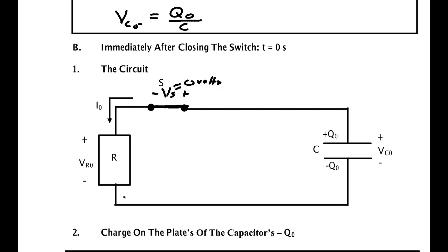I wouldn't guess and bet my life that this circuit is working properly and isn't faulty if I'm working on the back of a TV. People who work with them know what they're doing. An electrical engineer or physicist knows how to short the capacitor in a safe way to guarantee that it has no energy so that they can work on it. If you don't know what you're doing, keep your hands off of the cans. It's a very famous saying for people to protect themselves when working with electrical circuits.